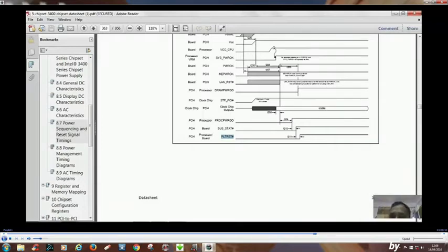If it is a PCH kind of board, identify which kind of PCH is connected. If it is an Intel series 5 chipset, then look for the data sheet of the Intel series 5 chipset. If it is an HM67, look for the Intel series 6 chipset.